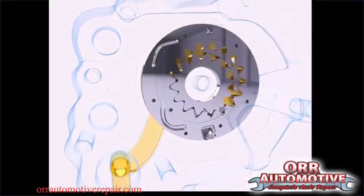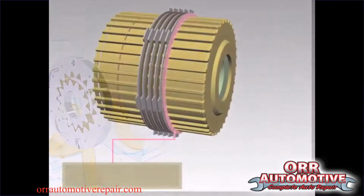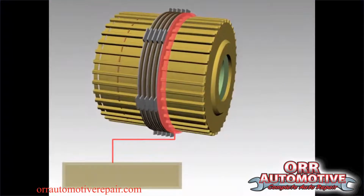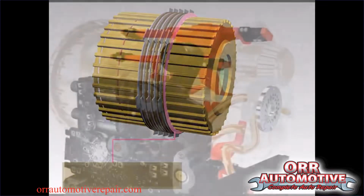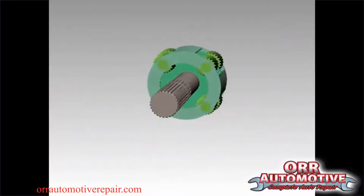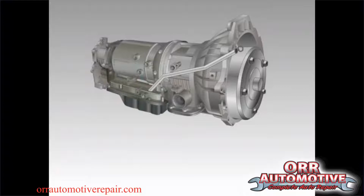Automatic transmission fluid is pressurized by the transmission oil pump that is driven by the engine. The pressurized fluid flows through the transmission to engage and disengage the clutches and actuators. A valve body, usually located at the bottom of the transmission, controls the fluid flow to these clutches and actuators. Clutches are attached to the planetary gear sets that create the different gears in the transmission.